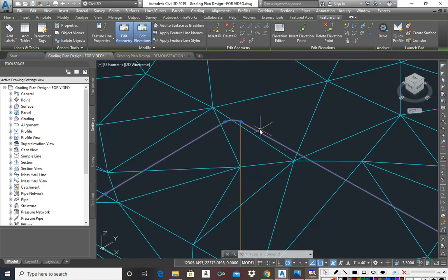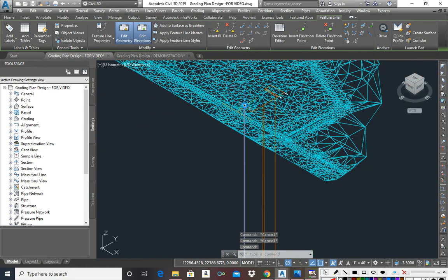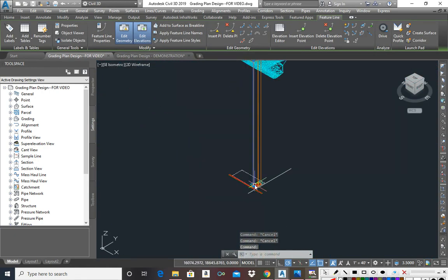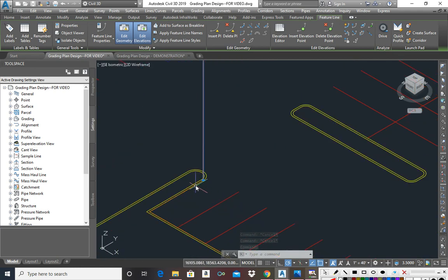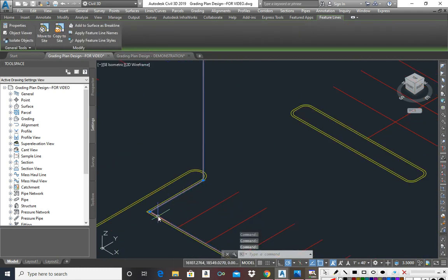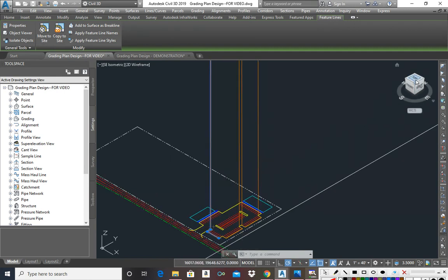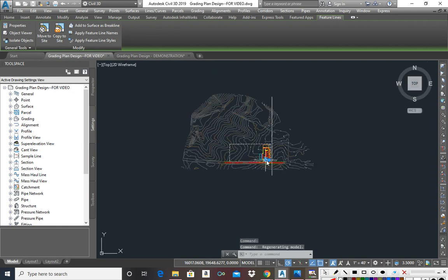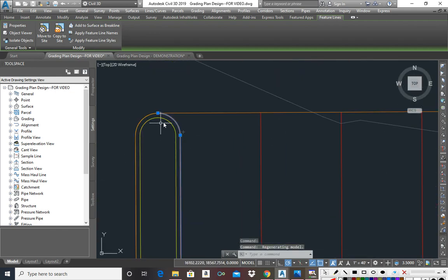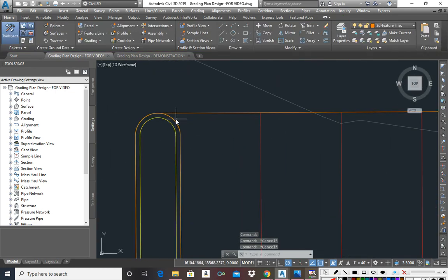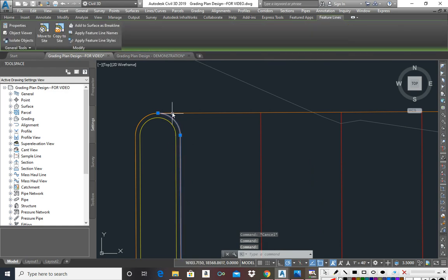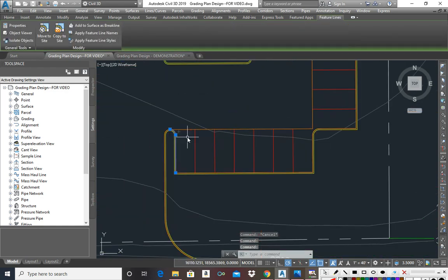What is happening with these other ones? Well, these other feature lines, like these, for example, we don't have to do this. Let me just show you, are going from the elevation of that base feature line, that's just a term that I came up with, to 0. So that is correct because I haven't set those elevations yet. So this baseline elevation has been set. This one and this one have not. So those are the ones I need to work with next.